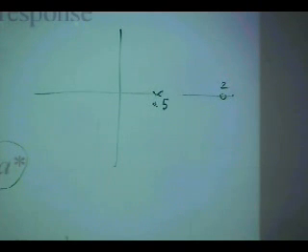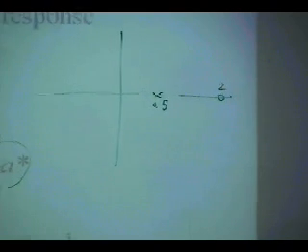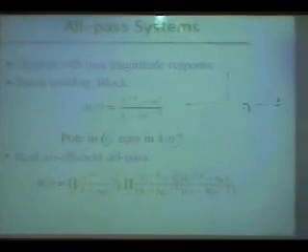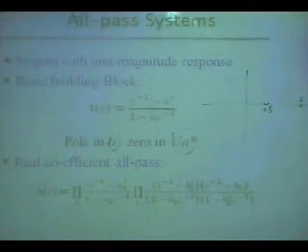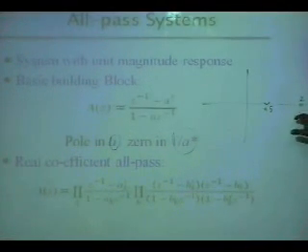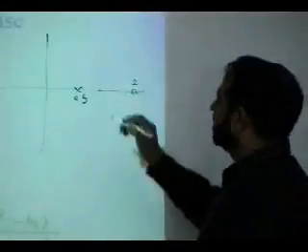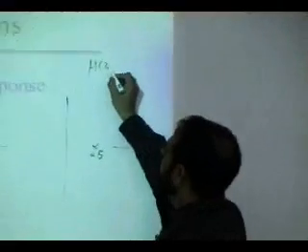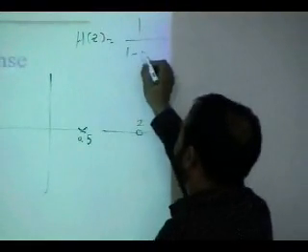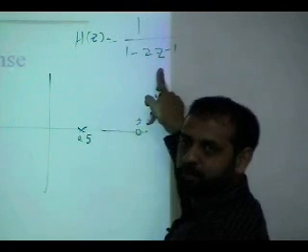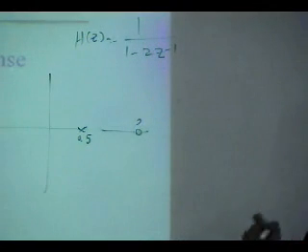So this is useful. An all pass system is useful because it's not going to change the magnitude response. So you can place some poles and zeros to your liking. If they can cancel out something, especially a 0 here can cancel a pole at this location. So you have a system H of z which has a pole which you don't like, and you want to cater for this pole. You say, I don't like this pole because it is outside the unit circle, it's making everything unstable.